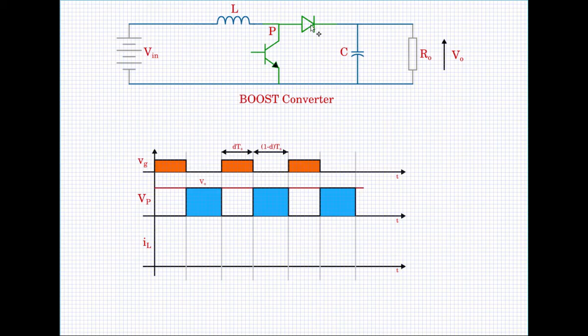That is one rating you can have for the diode. Likewise for the BJT, when the BJT is off, the diode is conducting, and the V0 value comes in here, and the BJT should withstand V0 during its off condition as seen from this waveform. So the voltage ratings for the two devices can be obtained from the pole voltage value.